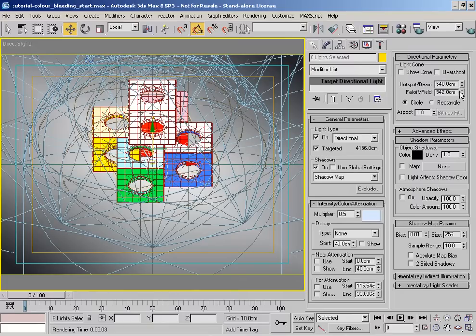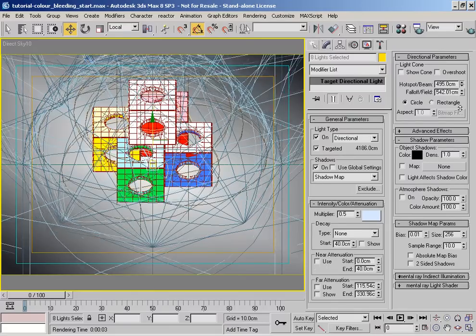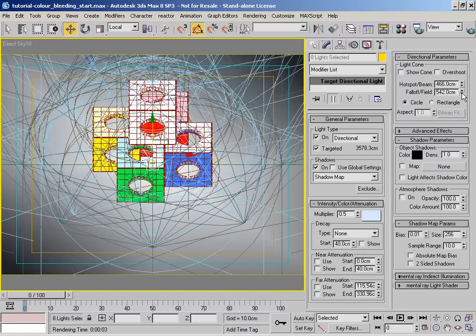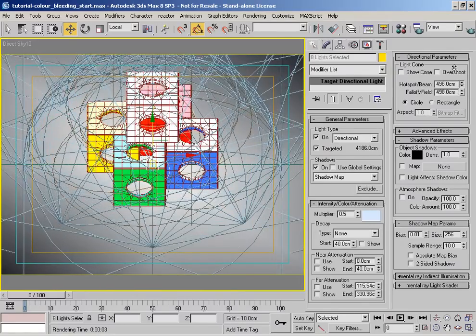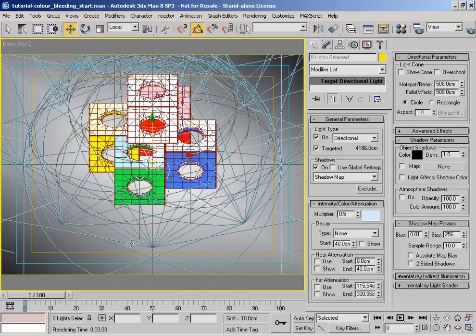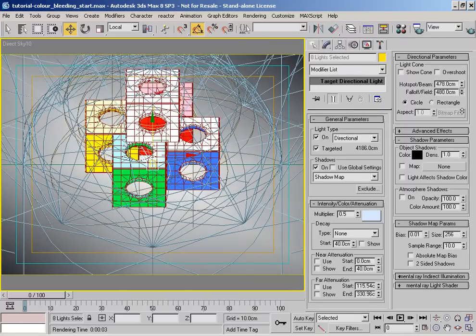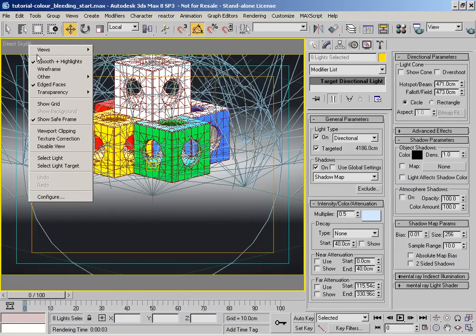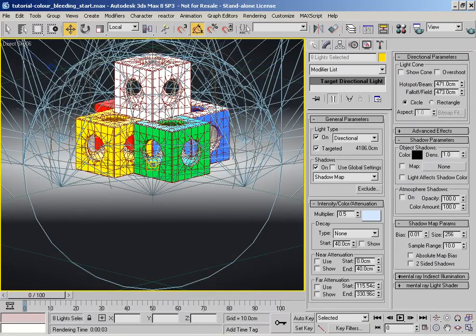So we don't need to worry about the falloff, the internal hotspot beam. So you'll see this internal part here, that's basically where our multiplier is at full strength, and that's obviously where the throw is down to 0. So we obviously want to get close to using as much area as possible for our boxes. So we can actually just tighten that off a little bit. Let's just bring that a bit closer, obviously checking other lights just to make sure that we've still got everything. That's almost clipping the top, but that should be okay.